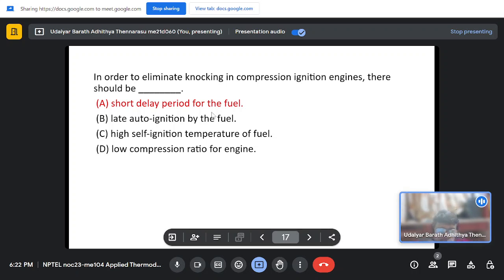So you are essentially reducing the ignition delay time. This will ensure that there will be self ignition in the diesel engine. That's what is required, and having this short delay will create a flame that will propagate, and it will create the uniform combustion which is required. So in a compression ignition engine or CI diesel engine, the fuel should have a shorter ignition delay. That's what having a higher cetane number gives. So you need a higher cetane number.